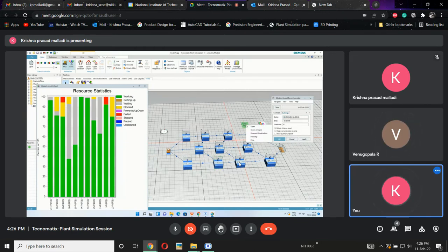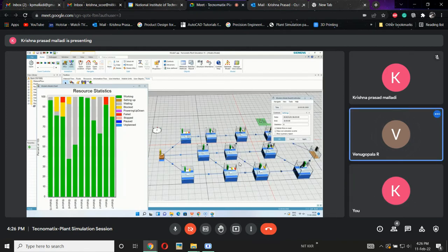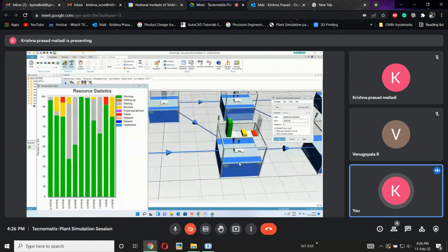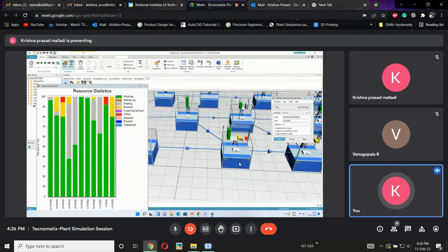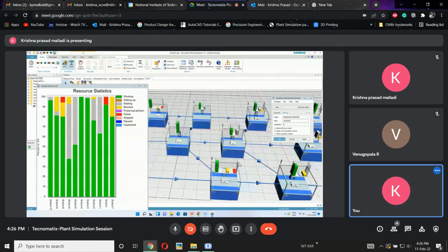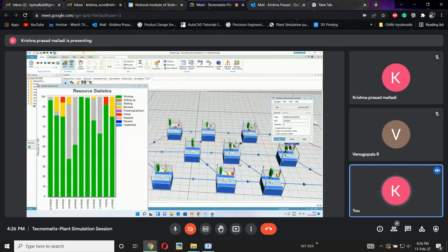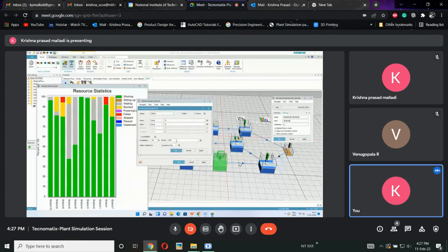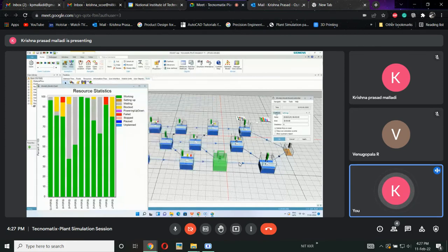If I click show analysis, now there is a red mark also. In the bottleneck analyzer, I can directly calculate this. Previously, for this machine there was no failure because we hadn't assigned any failure. We have assigned a failure for this one, so it was enabled. Similarly for this machine, if I double click, failure, new, 95% and 1 minute, apply, okay, okay, and we need to reset the simulation and run it. Now the third machine's failure is also considered. Now this will be the realistic model.